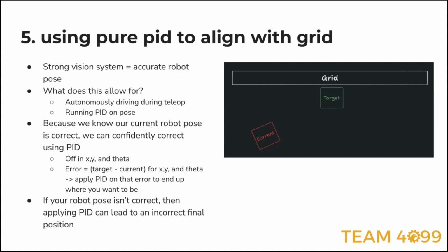You can also do closed loop control on your Apriltag work if you generate a trajectory for it to follow from point A to point B, and then you can follow that using some feed forward values for your wheels as well as PID. So you don't necessarily need to do that. If you're just on a straight line, PID will work perfectly fine for you. But if you want to do farther away movement, if you want to do curves, stuff like that, it's really important that you use something like a feed forward as well as PID.